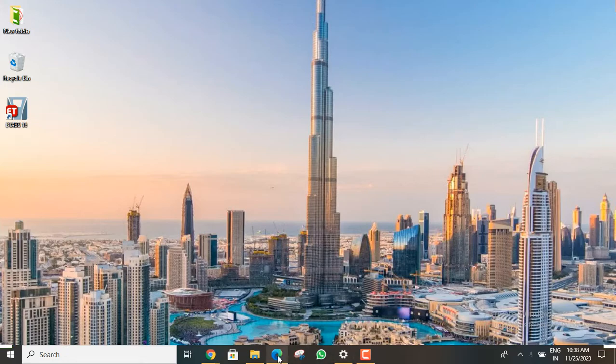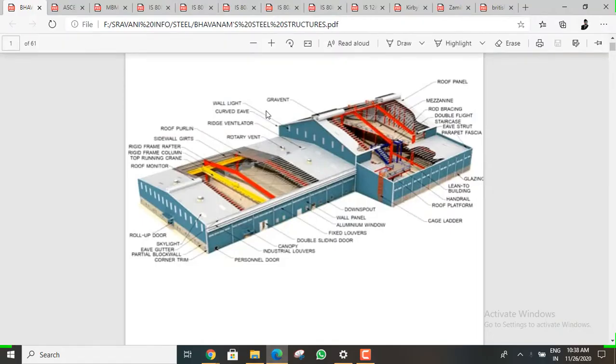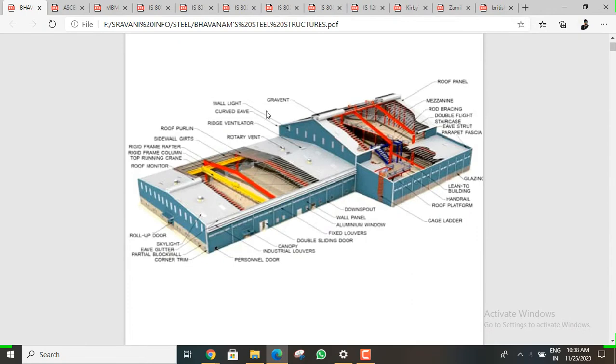In this session, we are going to discuss steel structures. In steel structures, we have different types: one is conventional steel and another one is PEB. What does conventional steel mean? Whenever we study BTech, we already know about conventional steel, that is I sections, ISMC, ISJC, and these are all conventional steels. Those all have standard sizes and can be fabricated directly in steel plants.